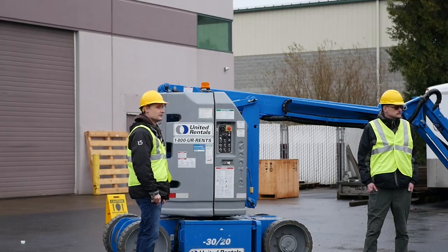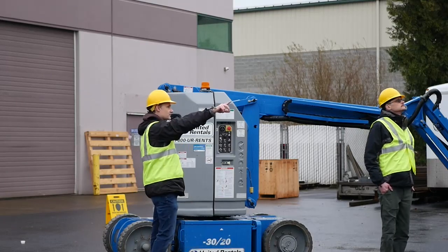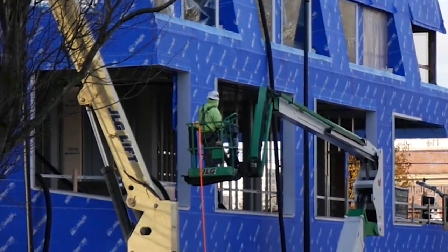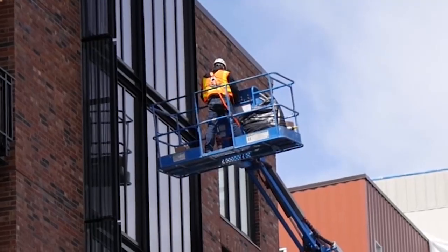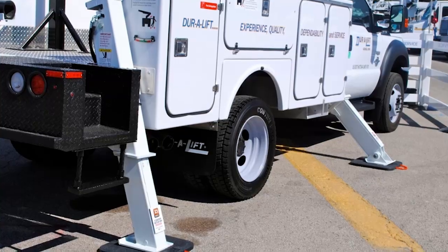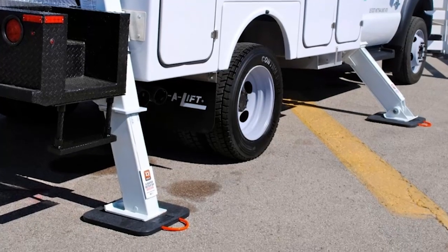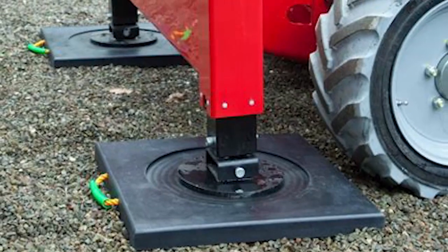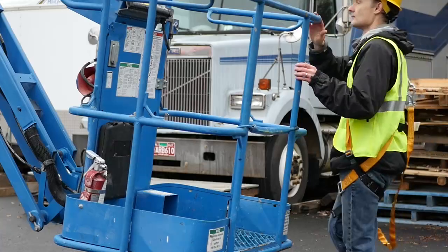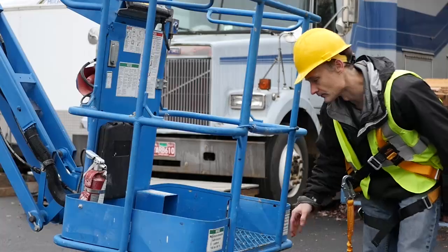Check the overhead workspace, to make sure that it is clear of obstructions, or electrical conductors. Maintain a safe distance from any obstructions, or electrical equipment. Try to keep the load evenly spaced on the platform. Engage the outriggers, and stabilizers, as required by the owner's manual. Use outrigger pads, when necessary, to provide firm footing. Make sure the guardrails are installed properly, and the gates are closed.